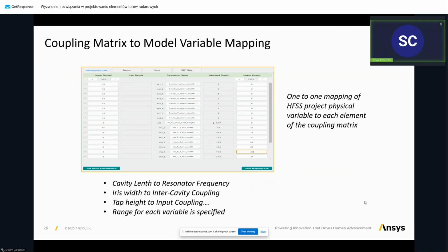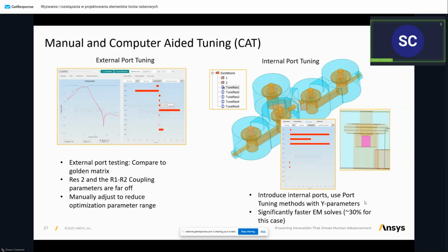So you'll see the parameter list if you use this tool. The parameter list is here that will correspond to the HFSS structure control, and any of these things can be changed. Here you can see when we run our first run through the computer-aided tuning example, we've got a stack of the parameters that are tunable here, and it shows us what appear to be the errors. It takes an assessment of the errors of any one of these parameters for comparing the filter's measured response against the ideal response, the developed design response.